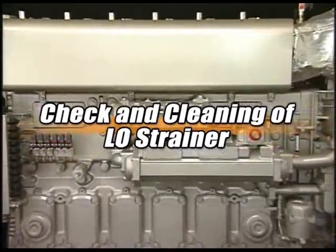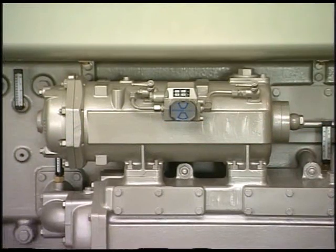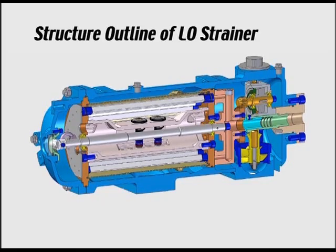The lube oil strainer fitted on this engine is the automatic backwashing filter. I will explain the mechanism by using the sectional view. Lube oil is filtered by running from inside to outside of the strainer element. The cleaning nozzle rotates during the operation by the turbine that is driven by the lube oil pressure. At the tip of the nozzle, the flow of the lube oil is reverse, dirt is discharged, and filtration and cleaning are constantly repeated.